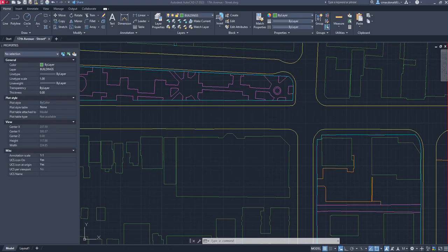So we're back in AutoCAD. Let's say we're happy with how much we've pared these lines down. We're happy with the amount of information that we would be importing into Illustrator. But there's one easy step that we're going to take before we actually do our import. It's really important for you to have your lines, your polylines, be as complete as possible so that they'll import to being the most complete shape possible in Illustrator.